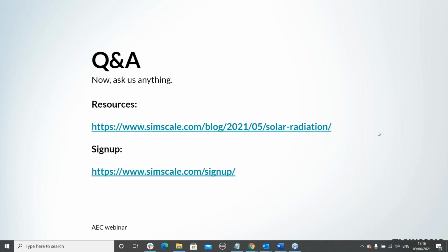So it's literally just a boundary condition addition to the physics of the study itself, and the runtime and the computational power is not going to vary much, although there might be a slight difference between the normal case study without the solar load and with the solar load. Based upon experience, this is going to increase about 2 to 5% of your computation time and also the computational effort or cost.